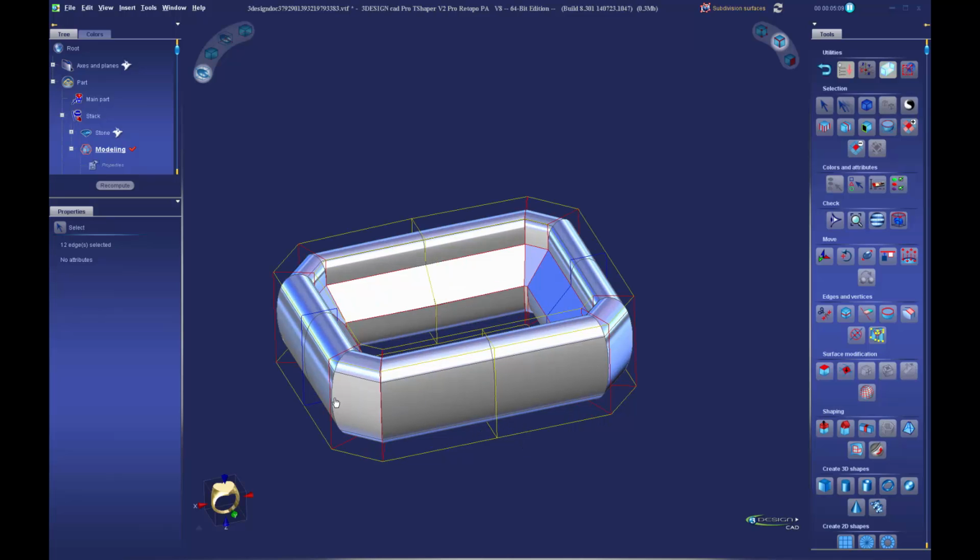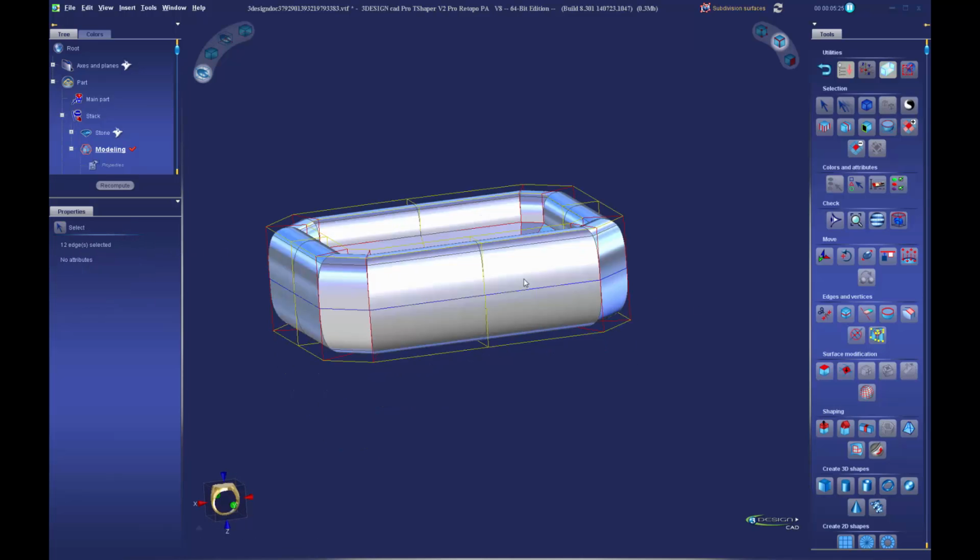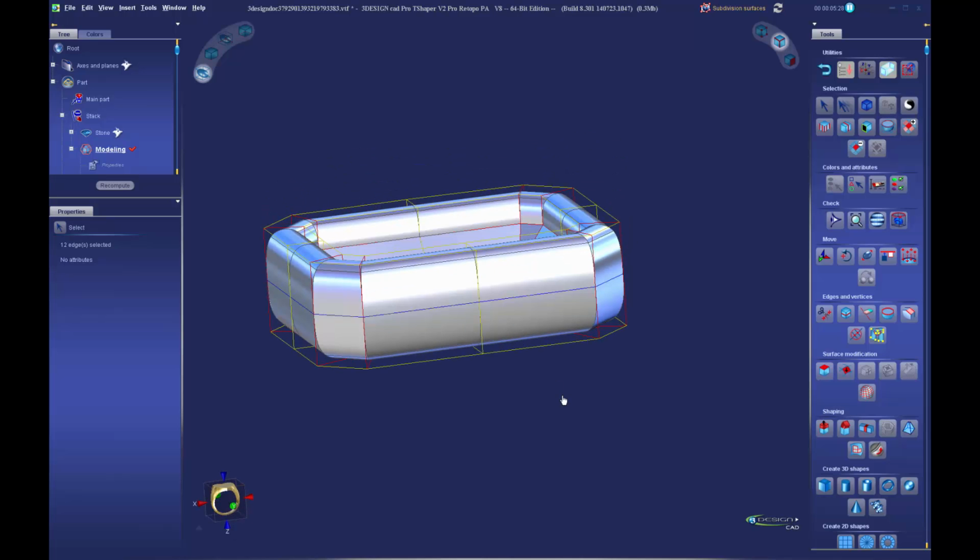Go ahead and split it across the midpoint around the bezel as well. Just the outside. We're going to select this vertical edge right down the middle, do another edge ring, and one more split and pull. So that'll subdivide it into 2 parts. Gives us, again, a little more control over the shapes we can make.